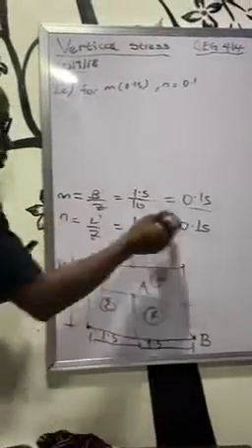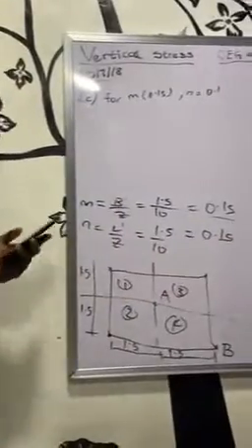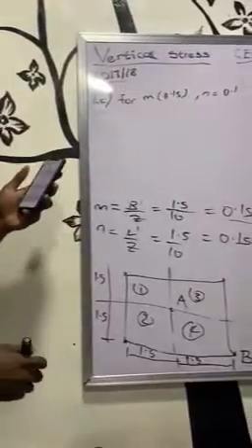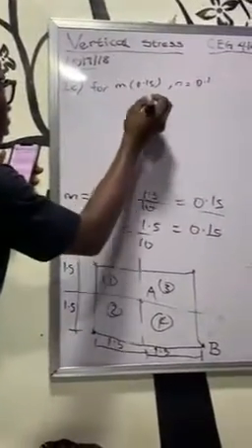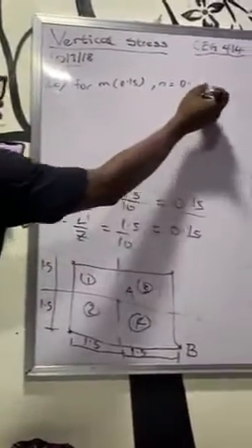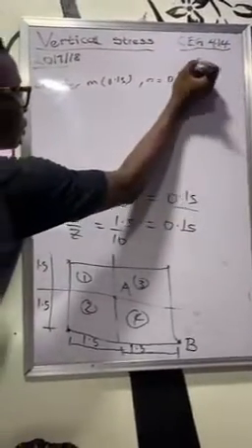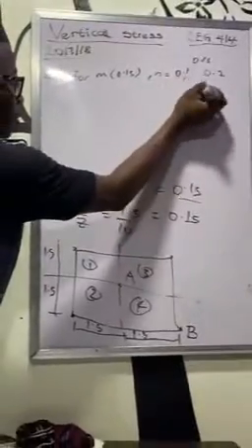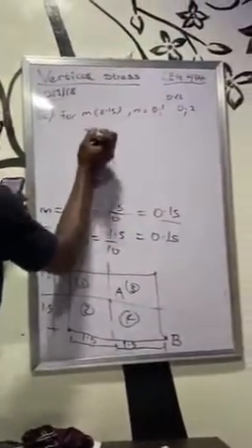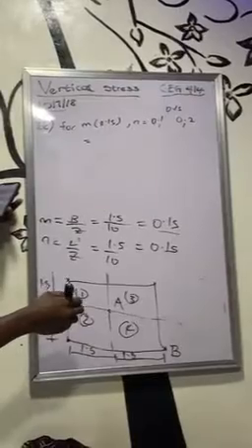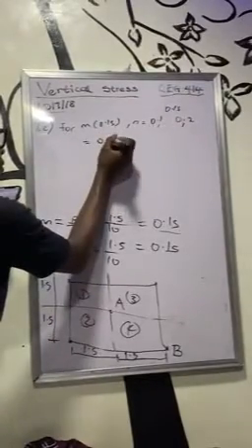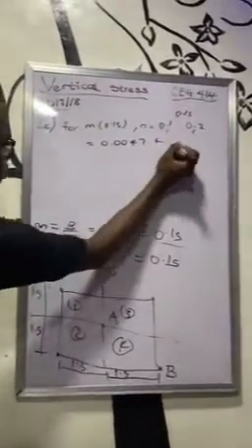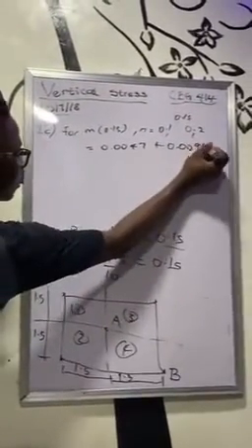So here we have our M at 0.15, our N at 0.15. I'm checking through the table. I have a sample of the table with me. We don't have 0.15 on the table. So let's just hold M constant and find 0.15 of N. Since rather than interpolating, we can just add both of them together, one of 0.1 and 0.2, and divide by 2. So for N at 0.1, we have 0.0047. At N at 0.2, we have 0.00917917. I just divide by 2.